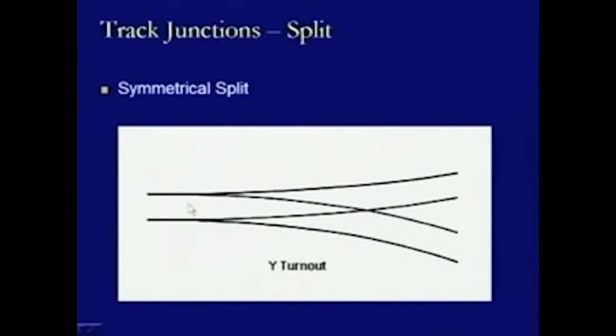Therefore, the train, the rolling stock, has the flexibility of taking a turn either in the left or in the right direction. And here what we see is that again we have one pair of points or switches being provided at this location, and because it is symmetrical in nature, there will be only one crossing being provided here. So, there is one crossing, one pair of wing rails, one pair of jack rails, and 4, that is 2 pairs of curved lead rails in the contrary flexure direction.